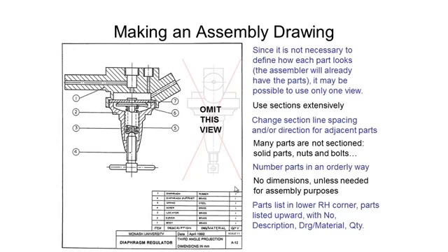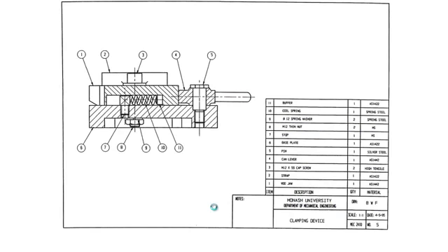If you've got multiple of the same part, so you might have 7 M10 nuts, you would put 7 next to your M10 nut description. So now let's take a look at our clamping device from back in the first video.